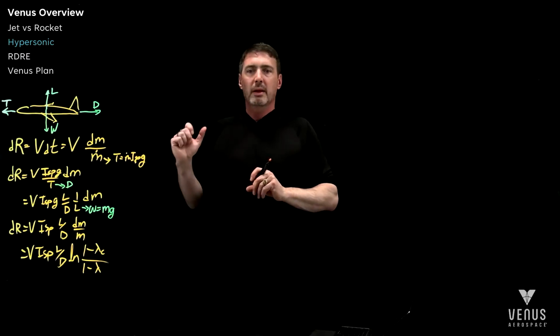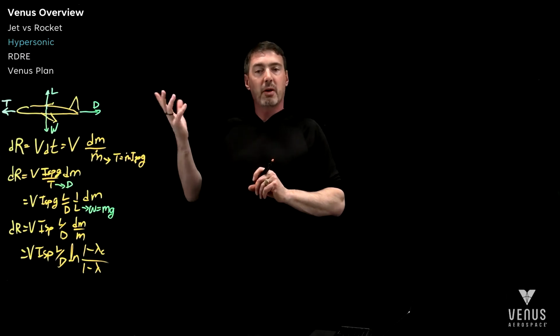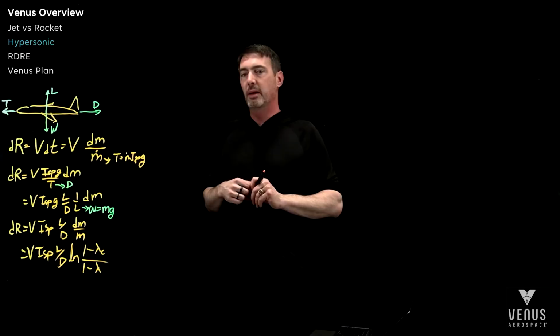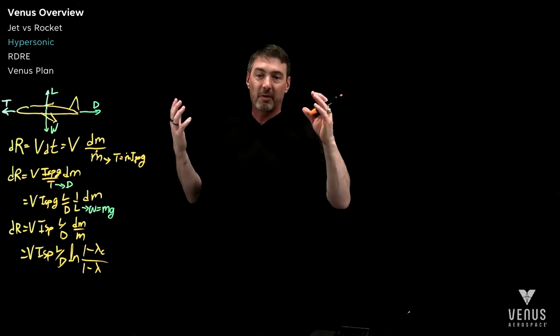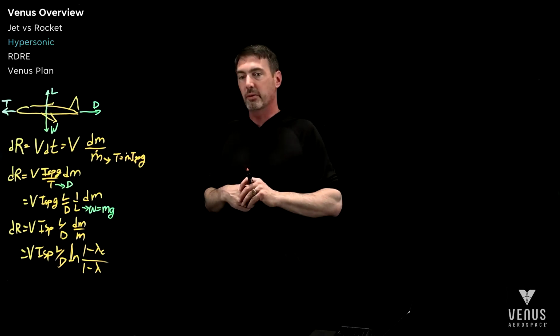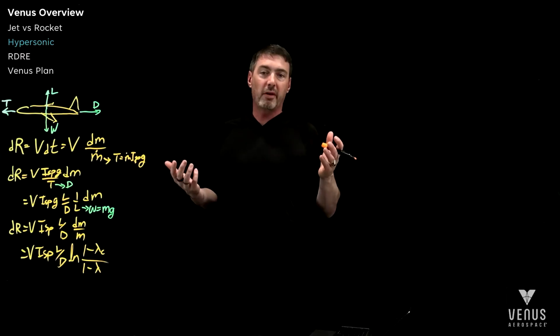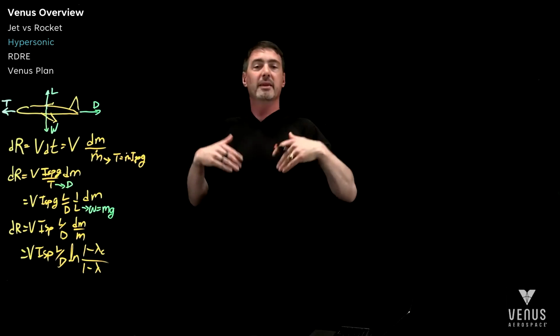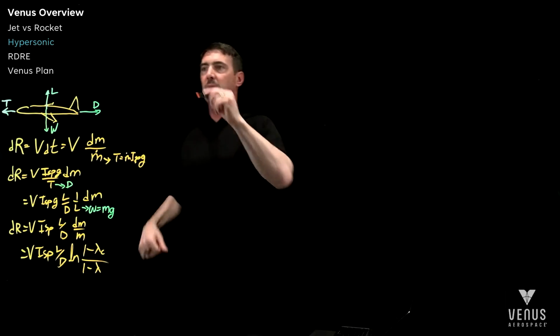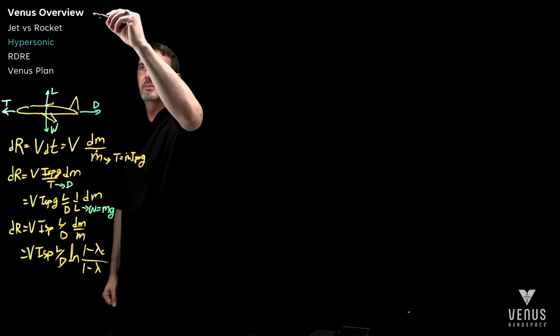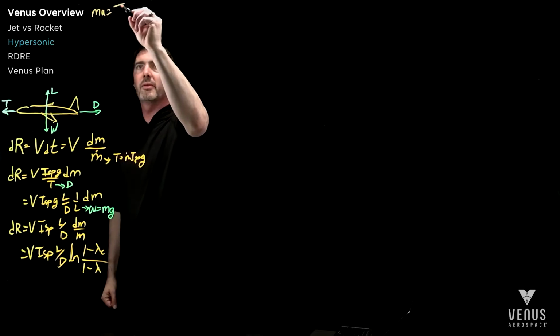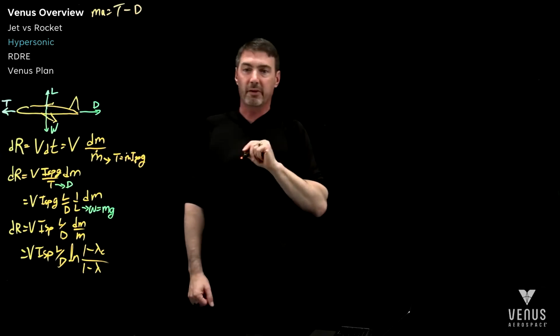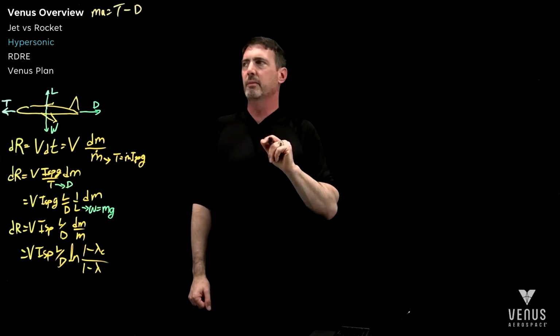Okay, so last time in the rocket equation we talked about the fuel to get to the top speed. So that's actually going to represent our lambda cruise. And so, when we're flying hypersonically, it does take a significant amount of fuel just to get up to the top speed, depending how you're getting there. And so you need to bring back up, again, that rocket equation. And so you had MA is equal to thrust minus drag, but this time I'm not going to cancel the drag. Still going to ignore gravity for right now.